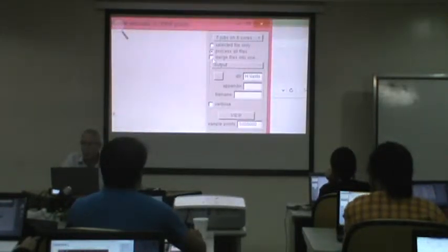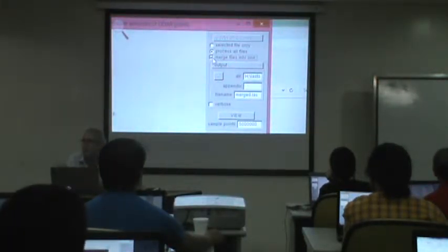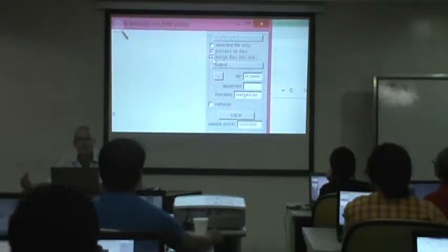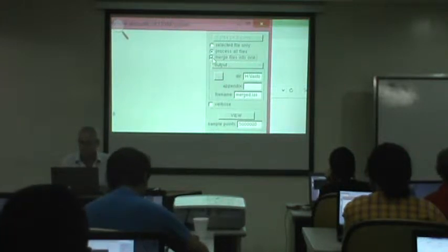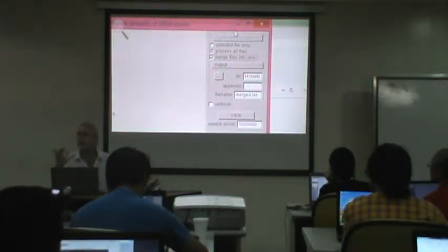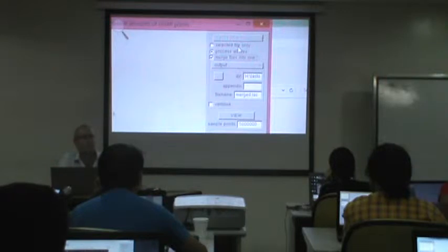You can always merge files into one on the fly. There's no need to actually merge them and create a copy of the file on disk, but they can be merged on the fly. When it's merged on the fly, it looks like one file. It's like one big LAS file. So there's no chance to run on multiple cores anymore because we have only one file input. That's why it's automatically grayed out.